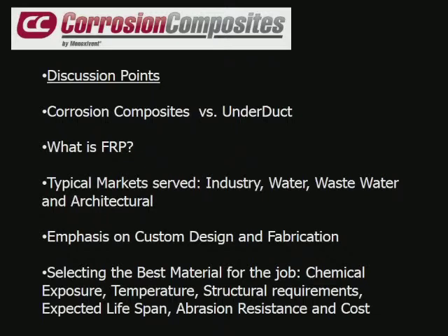We are definitely in the custom side of it. One of the most important things when you start a project is selecting the best material for the job. And the considerations would be chemical exposure, temperature, structural requirements, expected lifespan, abrasion resistance, cost. Those are the main considerations that you would start with.